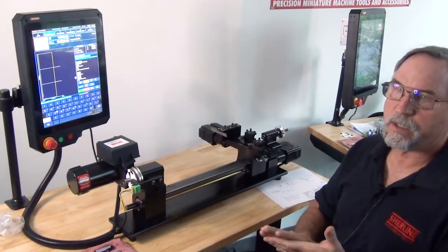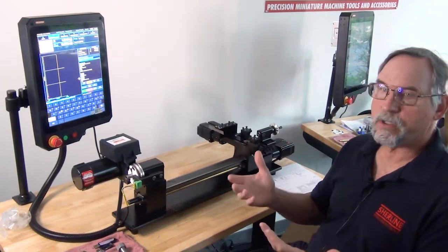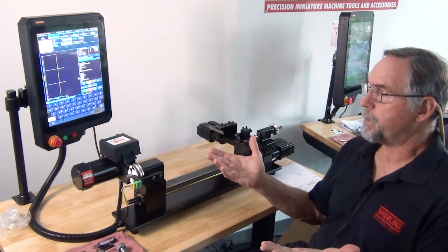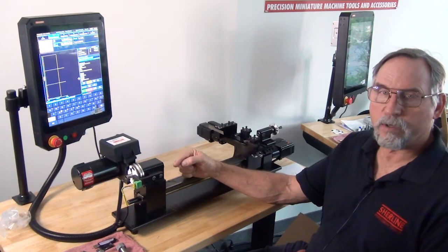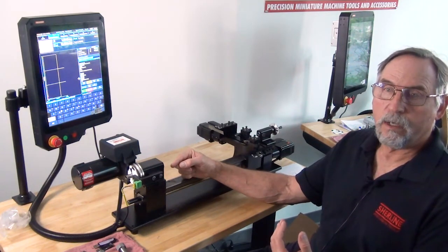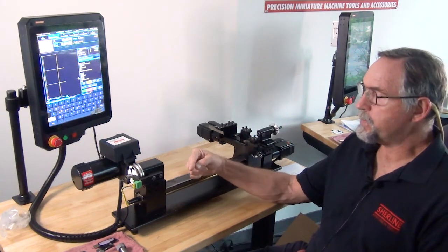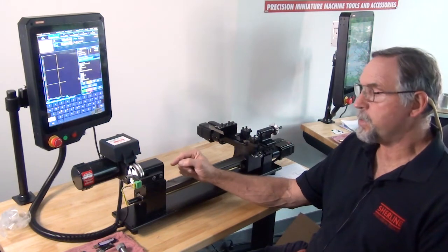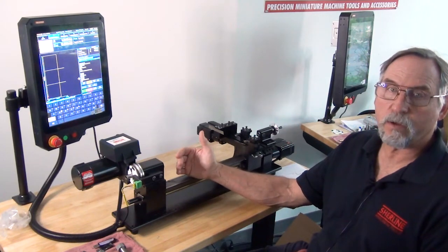Okay, so the other place that this comes in handy is if you're doing a facing cut, and if you're not using G96 and you just have an RPM in there, say 2000 or whatever, as it's getting to the smaller diameters, the RPM should actually be much higher. And you'll notice that if your RPMs don't change, then you're going to have a really nice finish on the diameters where the RPM is the correct range. And when you get closer to the middle, the finish is going to get worse, and that's because you're not spinning it fast enough for that diameter when it's facing it off.